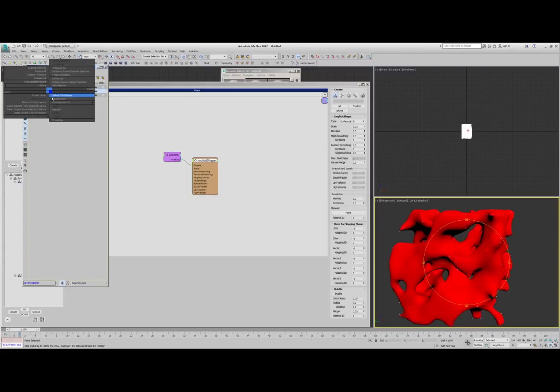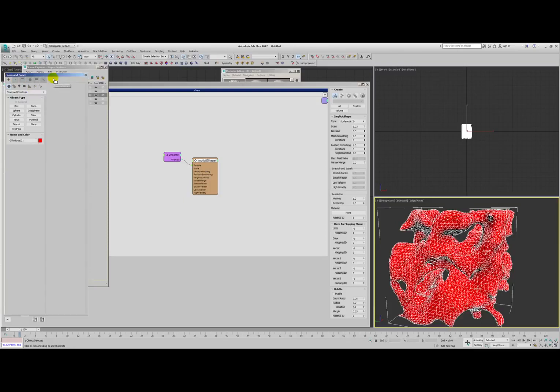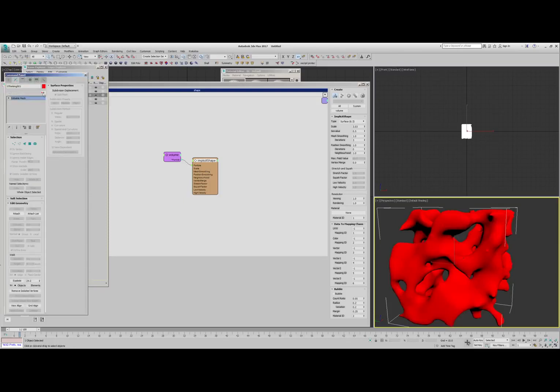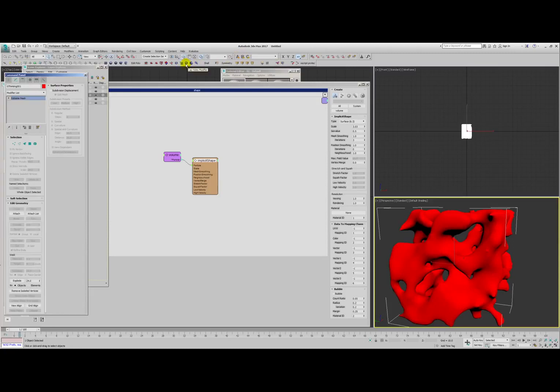Now what we can do is, I should have organized, there's just TP there. Let's make a layer for that. Let's also make another layer called results. Let's select TP. Results is the currently highlighted layer. Let's go tools, snapshot, bang, hide TP. Okay, so we still have this. Now it's just a plain old Max object, and we can throw whatever fun modifiers you want on it.